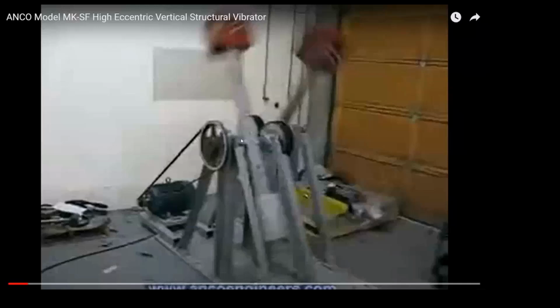Maybe, as I said, they may want to change the service load from residential application to industrial. I've seen cases where a hospital decided to use one of its floors to put in MRI equipment. The MRI equipment is really heavy and generates a lot of vibration. So they wanted to check whether the forcing frequency from the MRI will be acceptable.